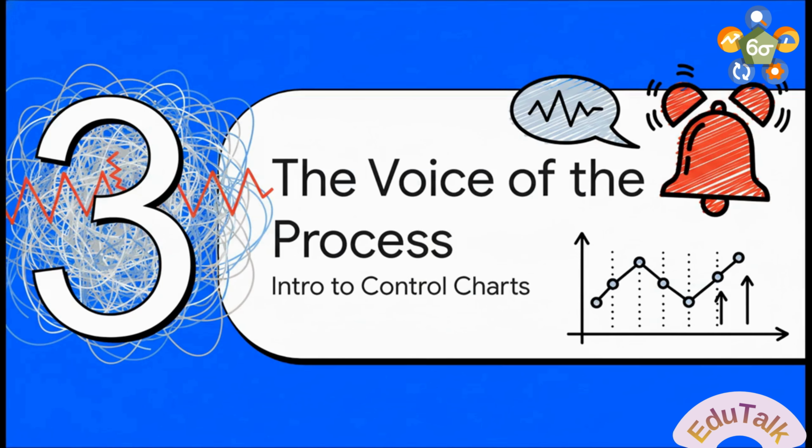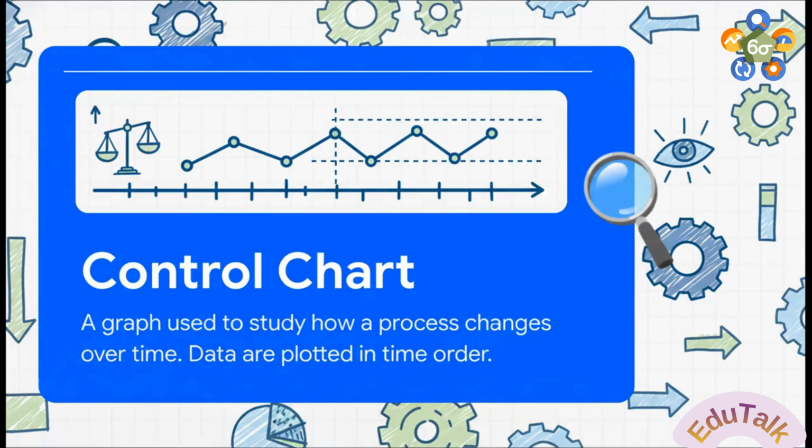So, that's the big question, right? How in the world do you tell the difference between the everyday background noise and a real, full-blown alarm bell? Well, that brings us to the hero of our story. Let's talk about how to actually listen to the voice of the process by using a tool called the control chart. A control chart is actually beautifully simple.